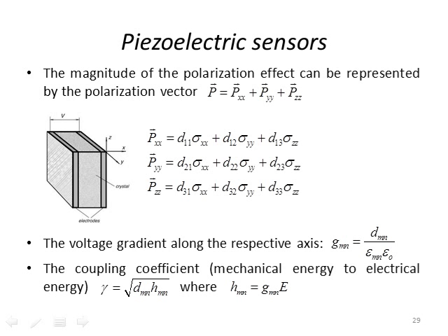Remember that the material is three-dimensional, so if it has three-dimensional properties, then you have to create these vectors, or actually these are tensors, that represent how the charge is going to change depending on how a particular direction of the material is deformed. Different materials will have different polarization vectors, and you can see that we have 9 different coefficients to represent the different charge that can be generated depending on the material.